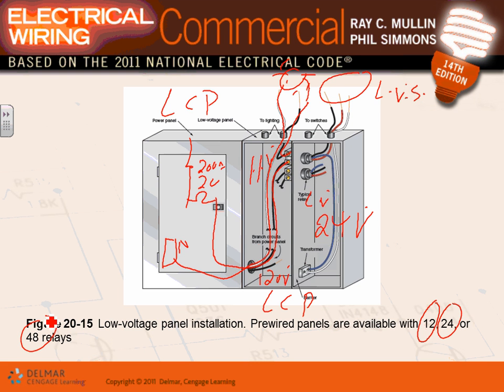You are looking at the lighting control panel. Here's my, this will be my lighting panel. This here will be my lighting control panel. Lighting panel, I don't know if you guys can see they're nipple-connected together here. So you can take the circuits, break them, and continue with your destination. Any comments, guys? Any questions? Comments, questions? The neutral, we don't break the neutral.